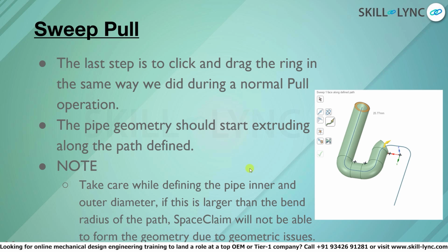It's important not to stress or panic. Go back, try to figure out exactly where your geometry is failing. Use the error logging function as I've shown you from SpaceClaim to figure out what it's having trouble with, and try to figure out how you can work around that or what specific feature is causing the issue, and edit that until it actually works for you.